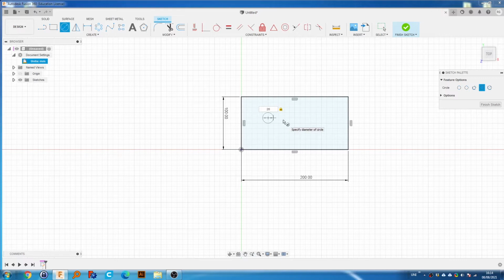It's also great to mention right now that even though our unit is millimeter, when we don't specify a unit, it will assume that our units are in millimeters. However, we can override Fusion's interpretation of the number by specifying a unit. So we can type in inch, and now Fusion's like, oh, inches. Or we could type in meters, and that's obviously massive. Or we could type in the units that we're using and it will scale to that. Or we could just put nothing in, and it will scale to that. Anyway, I'm just going to put 20 because I like working in millimeters.